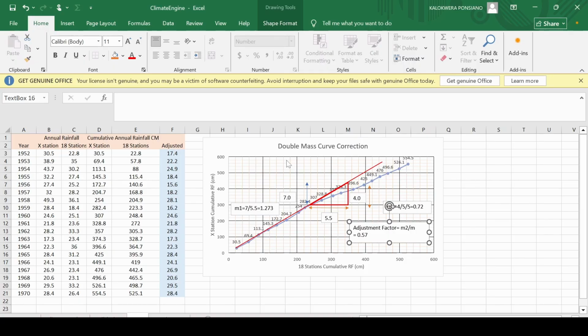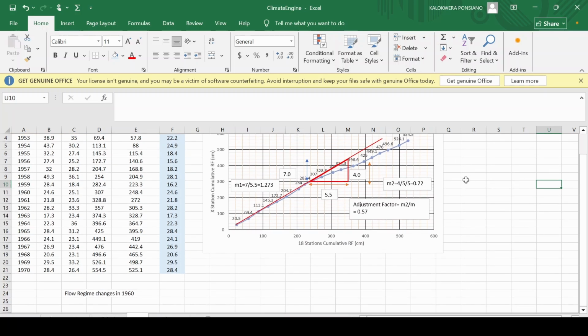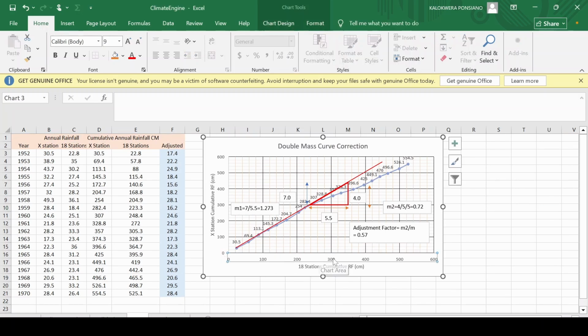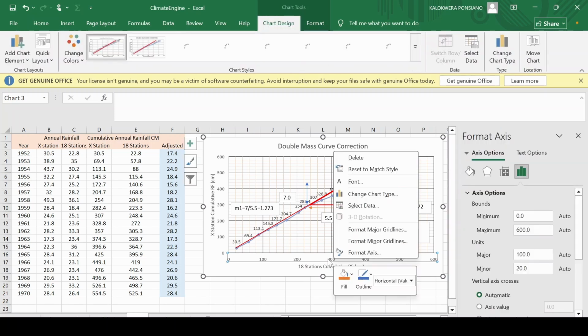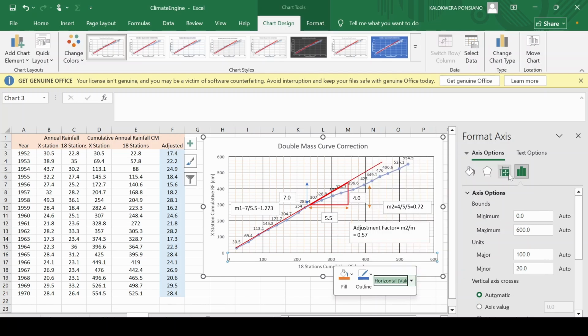Lastly, sometimes I also use double mass curve correction. I normally apply double mass curve analysis to check consistency over time. And you don't need math here, just the concept. It is basically the cumulative TRMM versus cumulative gauge. If the slope changes, it means there's inconsistency. And then you see how to address it by capturing the different slopes before and after the change. This step helps me detect bias before it enters the design.